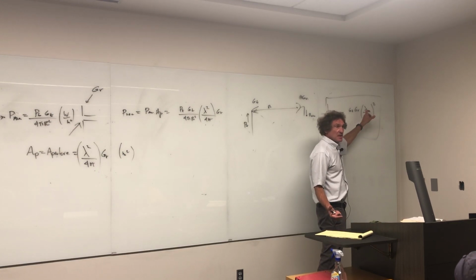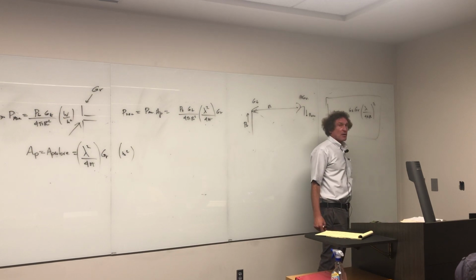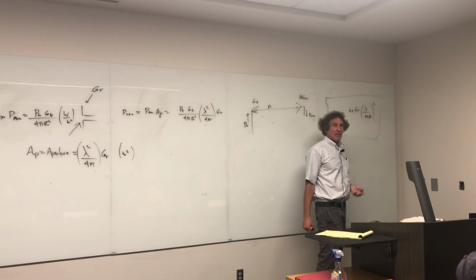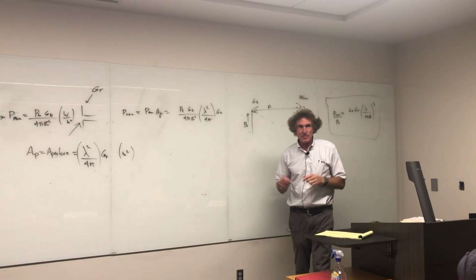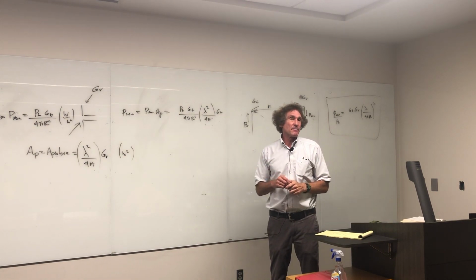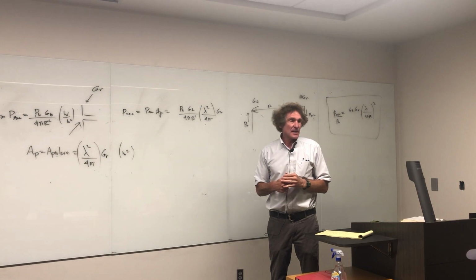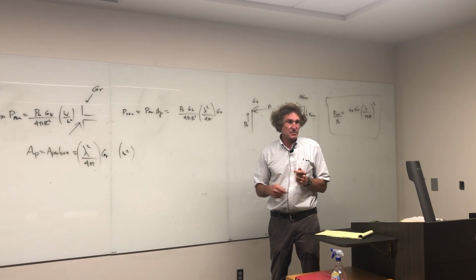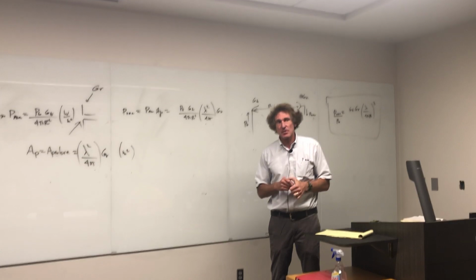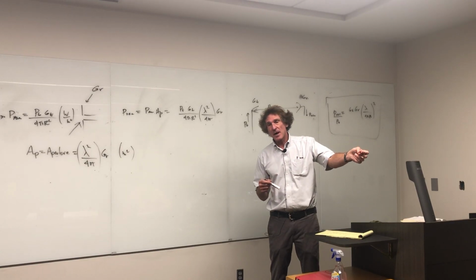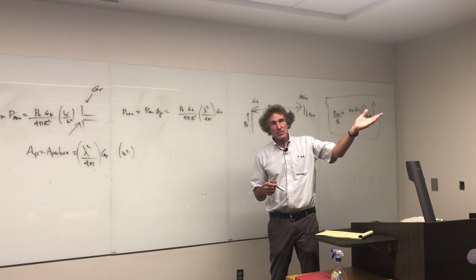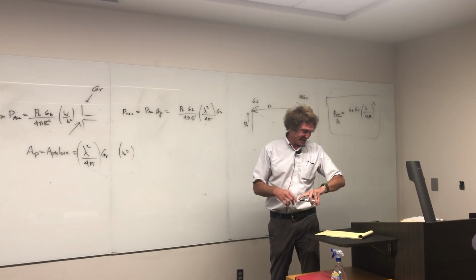But basically, you would multiply it by lambda over 4 pi r squared to get an idea of, and I use the word goodness, but it's an effective measure of how well your antenna system is linked to the other. It's used a lot for microwave communication systems. The Friis transmission equation allows you to know how much power any given antenna you're going to create can receive. And I'll get to more on this next time.